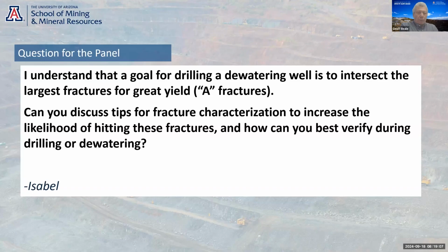Most fractures are highly variable, as is stressed in the course, and you can have a fracture or a fault zone with a yield at one location, and you move 20 feet away, and that same fracture or fault zone may not produce anything. The fractures may be healed, the fault may be pinched. So really, if you're going to spend a significant amount of money on a production well, there's no substitute for advanced drilling to characterize the fractures.